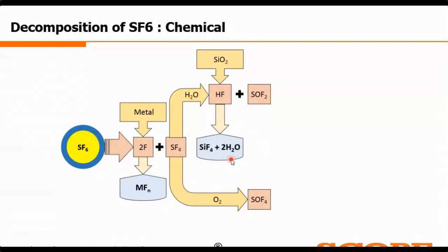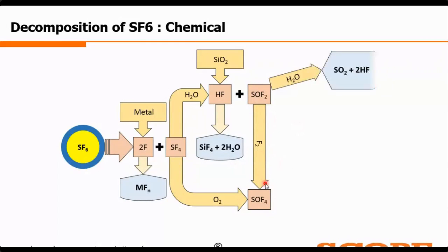So it is very important to know that moisture is the biggest enemy of SF6. You don't need moisture in your gas compartment, because once it is there, the reaction will start, and because of that moisture molecule, additional moisture will occur through the natural reaction. Now, SOF2 with fluorine forms SOF4, and SOF2 with the help of this additional moisture will form SO2 and HF.